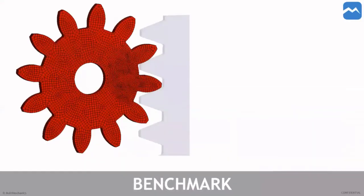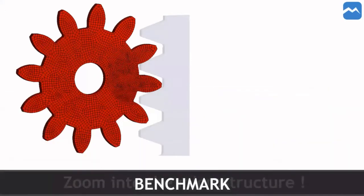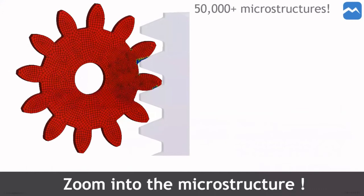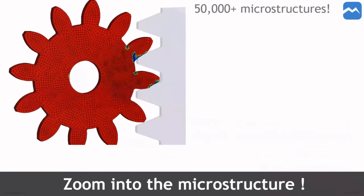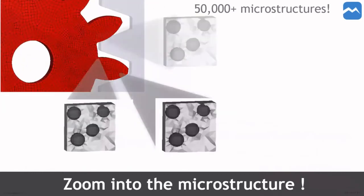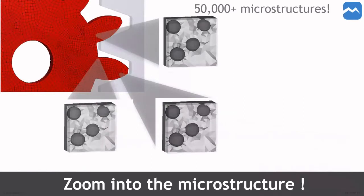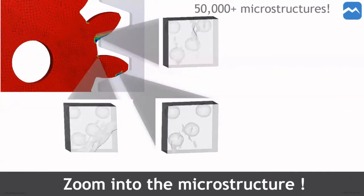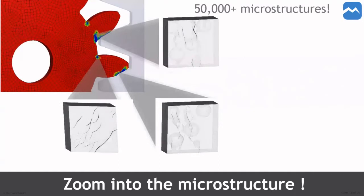Here's a benchmark to more accurately show what's going on with our simulations. Here we have a gear, and as it's being loaded, you'll see some blue, which represents a lower stiffness and the failed elements. If we zoom into 3 different integration points, we'll see we have 3 different microstructures. As the load begins to increase, you'll start to see different failure mechanisms originate in these microstructures in different ways. We see some have cracks going diagonally across the RVE, some going vertically and horizontally.